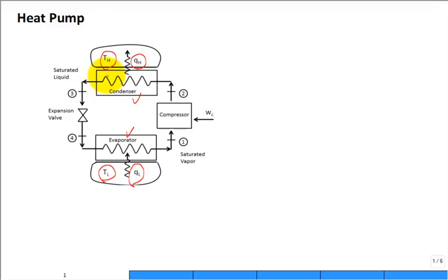It is. But the goal of the heat pump, this is what you desire. You want heat dumped into something that's already warm. And you're going to purchase maybe some electricity, and maybe this is the inside of your home in the middle of winter, and the outside of your home is a cold winter day. And the first time you hear about it, you say, this is ridiculous. Why did the engineer think that they're going to be able to make the outside colder and use that heat out of the outside plus the electricity to make the inside of my home warmer?